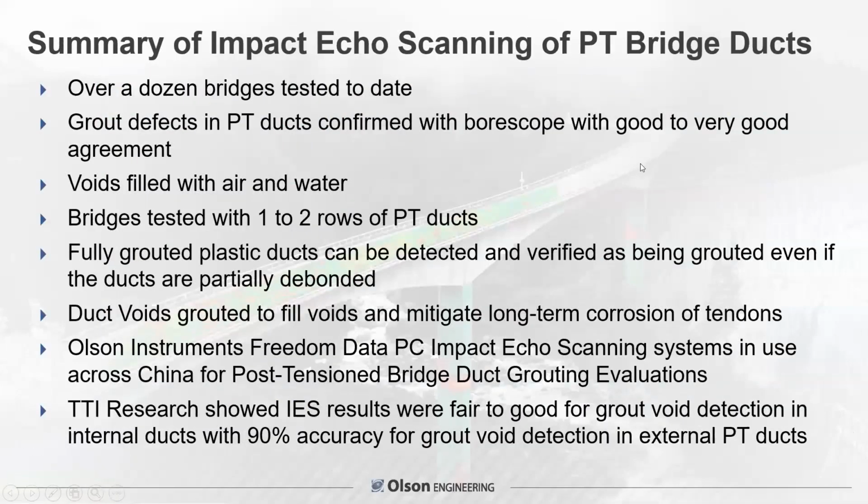So to summarize, for impact echo scanning of post-tension bridge ducts, we've tested over a dozen bridges. The grout defects in the ducts were confirmed with a borescope with good to very good agreement. We found voids that were filled with air and water. Bridges were tested with 1 to 2 rows of post-tensioning ducts.